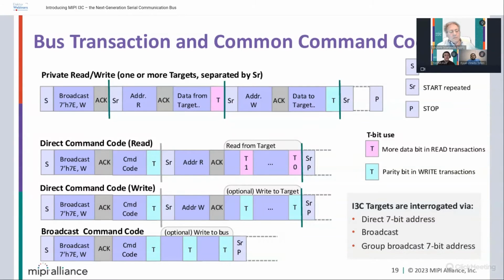And further along, there is the possibility in I3C to have broadcast messages. Broadcast messages are really of two kinds. One, you can address the full bus. Or sometimes it's useful to address only a subset of the bus. Let's say you want to disable or enable interrupts for three or four devices. So you can create a group, and then with the broadcast address to the group, you manage only the group.